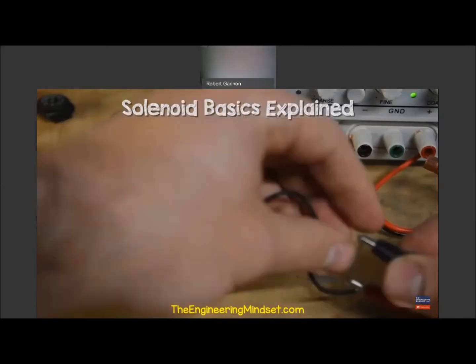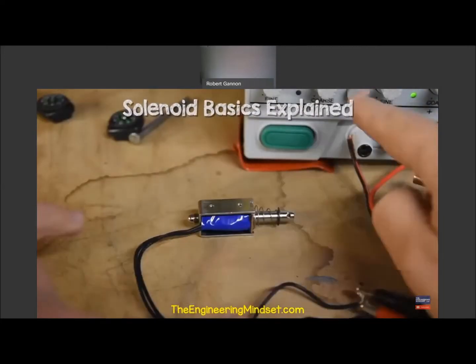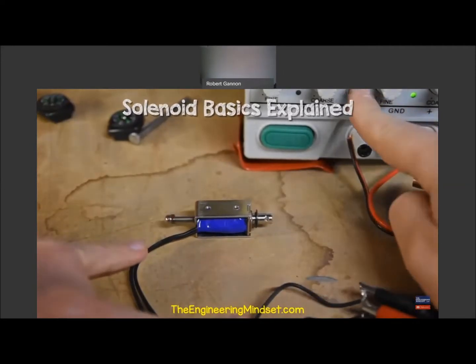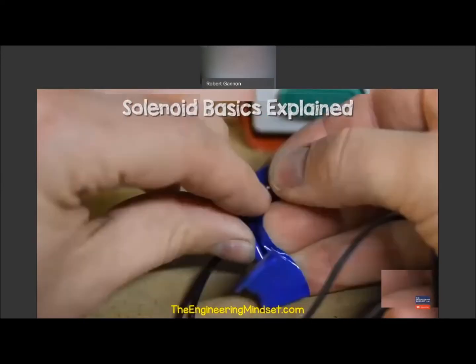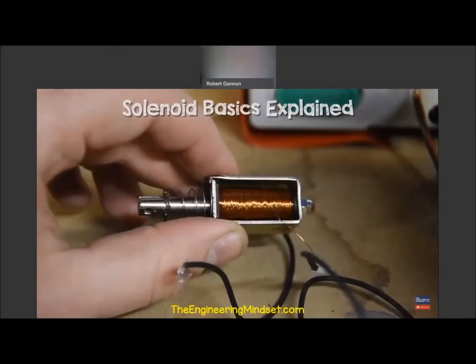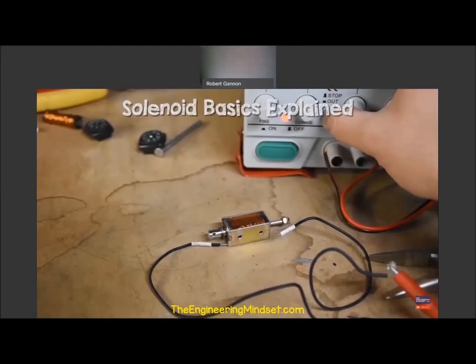If I connect this to a power supply, we can see that the piston can be pulled in by the electromagnetic field as soon as current starts to flow through the coil. If I cut the power, then the spring will force the piston back to its original position. I can remove the insulation tape to show that it's just the coil. If I then reassemble the solenoid and connect it to a power supply, we see that the piston is moved by the magnetic field and the spring.